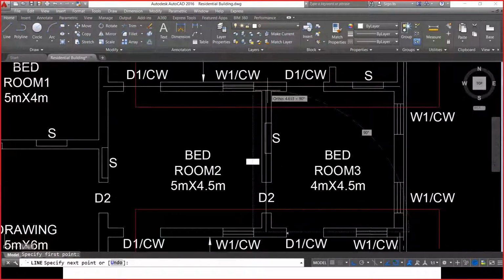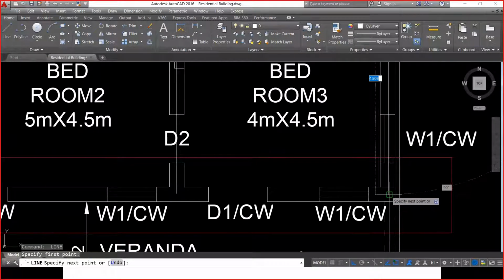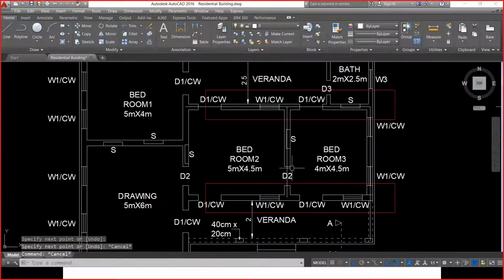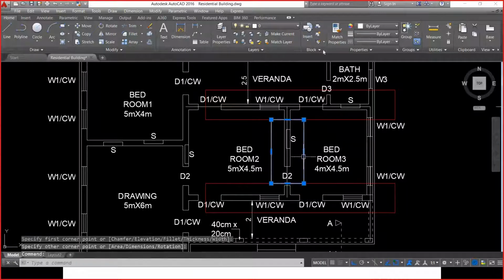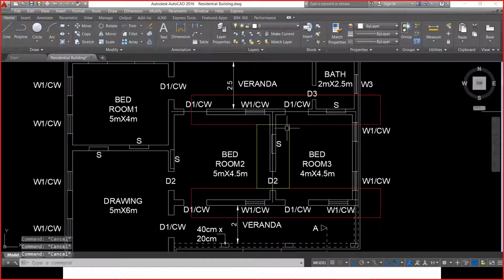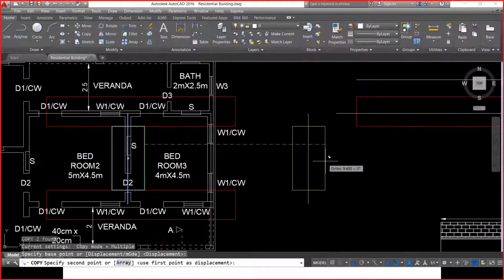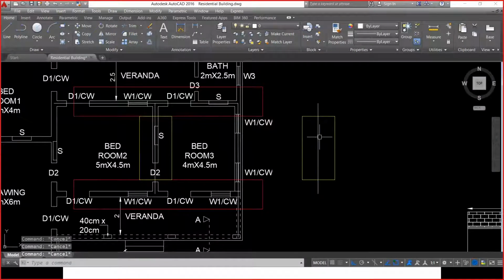I have calculated the center to center distance here and here. Now I am supposed to lay the lime concrete only to this area, which is highlighted in yellow color. But I know the length. This is the center line length, and this is the area I need to lay the lime concrete. I want the actual length. The actual length is from this end to this end.